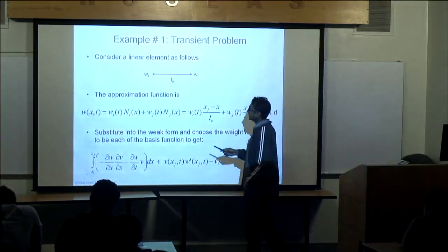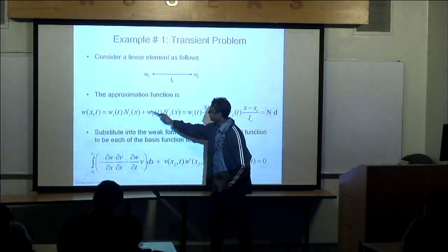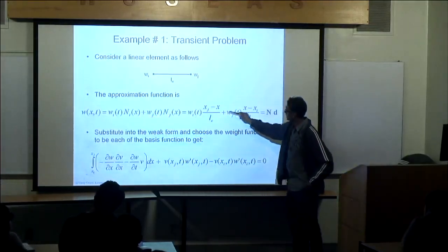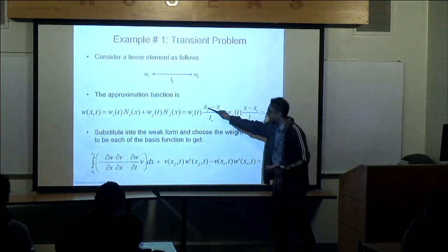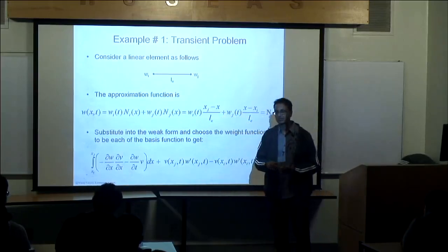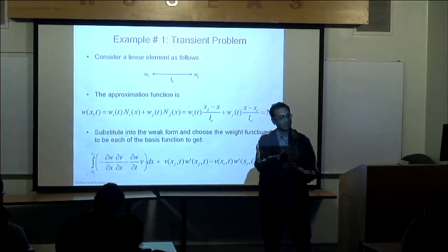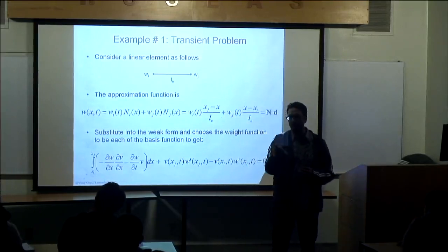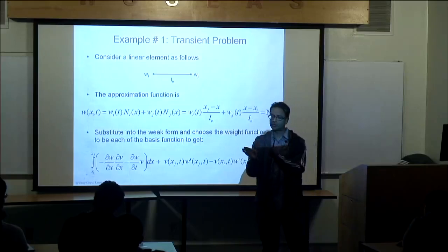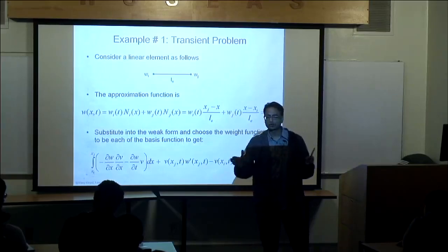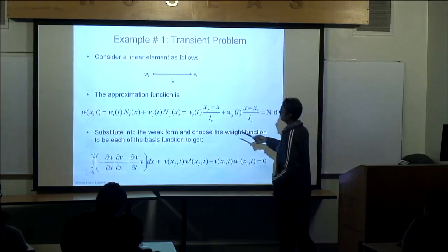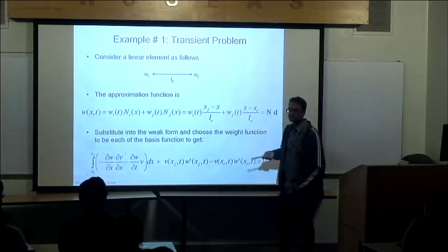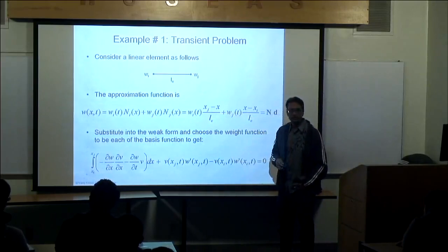And when I look at the shape function here, which you know for a linear element, we realize that the shape function is not a function of time, and I hope it's not, because I don't want my basis function to change as a function of time. We want to maintain that as a function of just the spatial coordinate, because again, we're just discretizing the spatial domain. We're using finite elements. We're not discretizing the time domain using finite elements. And you wonder, are these shape functions the same as what I got before? Yeah, absolutely. Let's see if it's true.